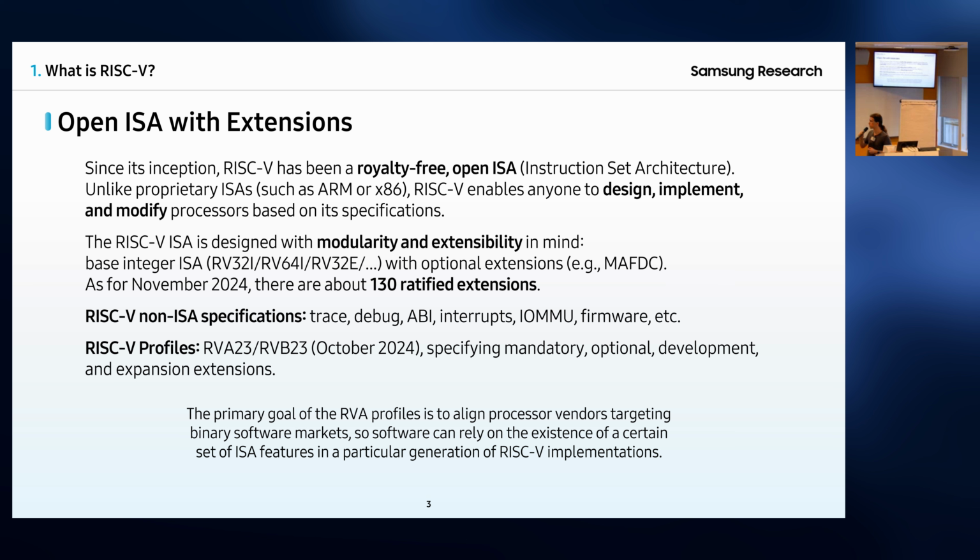So that's where RISC-V profiles come into the picture. Quite recently, in October 2024, RVA23 was ratified, which is really nice because it mandates use of the RVV extension. What profiles basically do is provide a solid base: a given set of RISC-V ISA extensions, some optional in some cases, which need to be provided by the hardware to be compliant with, for example, RVA23. So in the coming years, we can see some application-grade SoCs which support RVA23, and then Ubuntu, for example, can run on it.